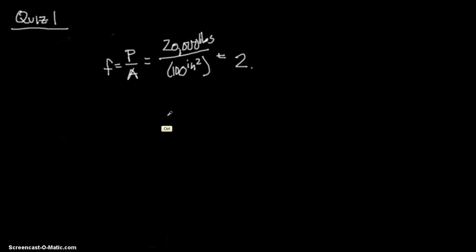All right, so that's not it. Not A. B, the maximum compressible unit stress used to design a member. No, I will say that's probably not the right answer. Some people sometimes use ultimate stress, but you shouldn't, and most of the time you'll use yield stress. C, the unit stress beyond which unit strain increases faster than unit stress. Well, that sounds okay. D, unit stress at which the material continues to deform with no increase in load.